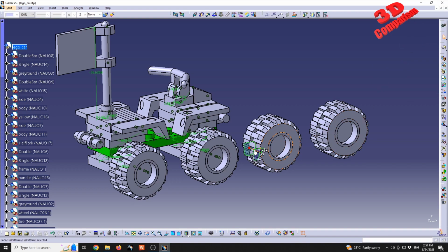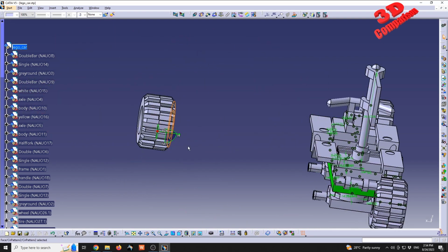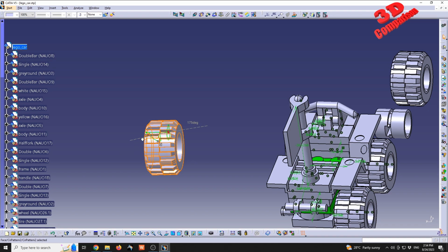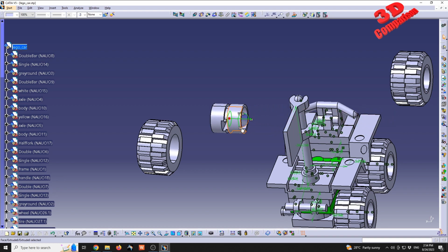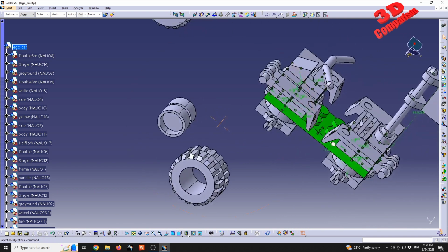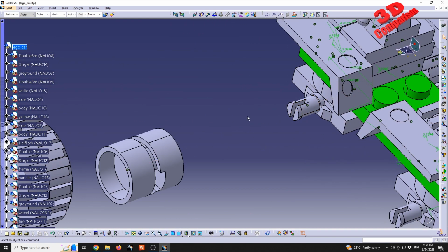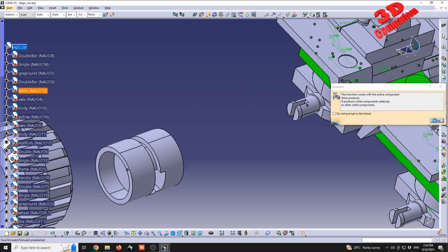That means I'm gonna move the component, and at the same time, when I reach over here, I'm gonna rotate it, but I'm gonna rotate it on the proper axis. So in this case it will be this one. It's not important that you fully define it, so I had 5 more degrees that I should have rotated, but it's important just to help the software a little bit in order to make it easier. If you can snap it all the way to 180, that's better. If not, CATIA will deal with that when we're gonna position all the elements.